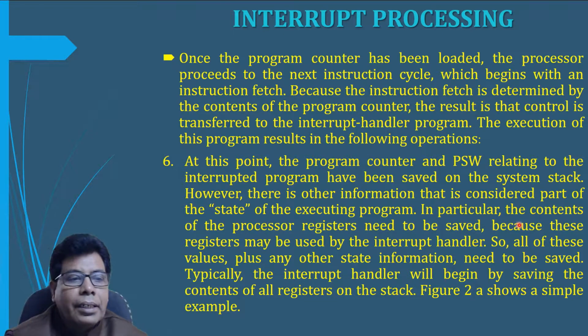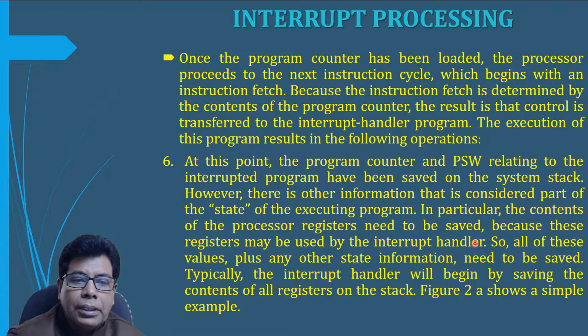In particular, the contents of the processor registers need to be saved because these registers may be used by the interrupt handler. So these values plus any other state information need to be saved. Typically, the interrupt handler will begin by saving the contents of all registers on the stack.